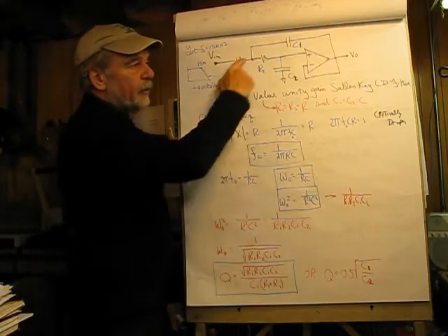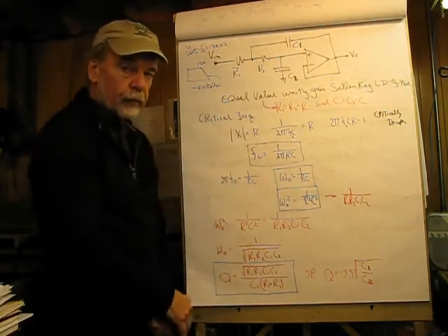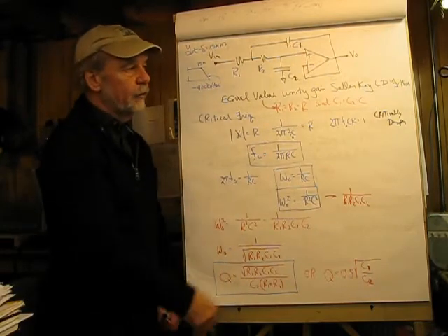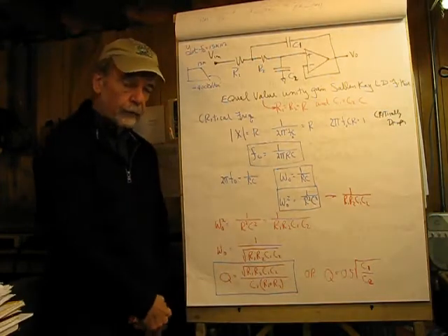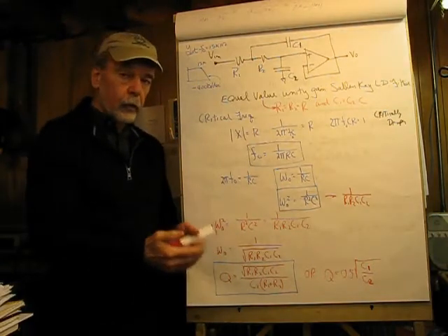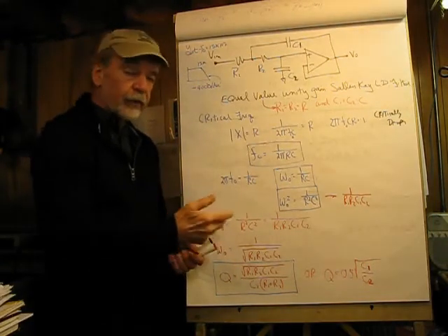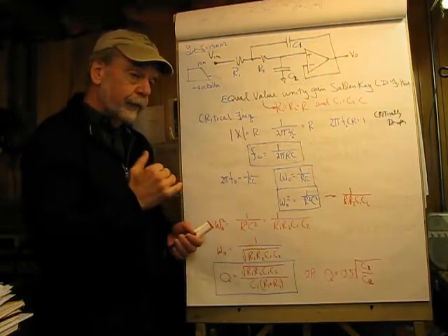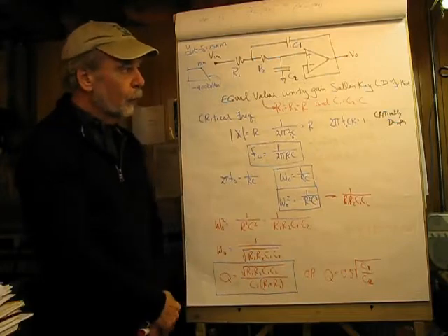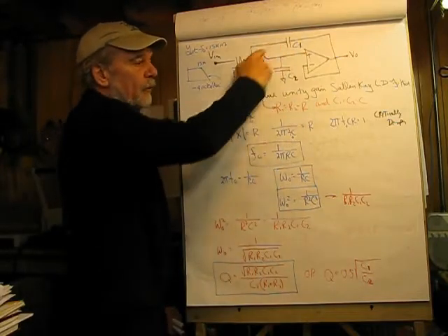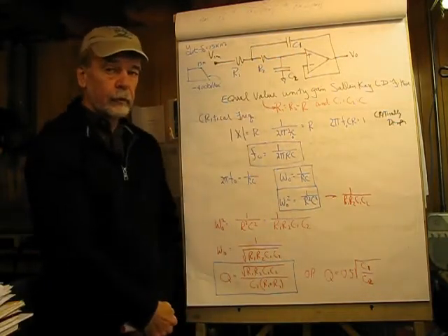However, if we connect it to the output, what we do is, it's called bootstrapping, we're going to feed some positive feedback into this guy, and what we can do with that, very important, is to control the Q, the flatness of the response, the phase of the response. And in some applications, phase is very important. So this feedback path makes this a very, very flexible filter.